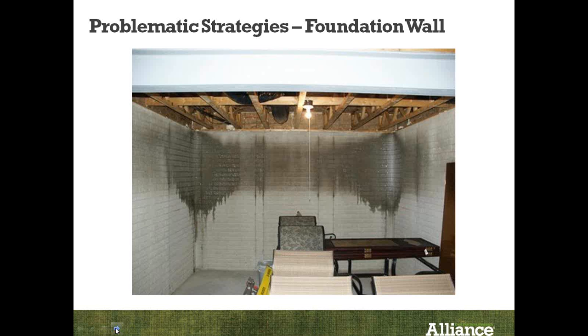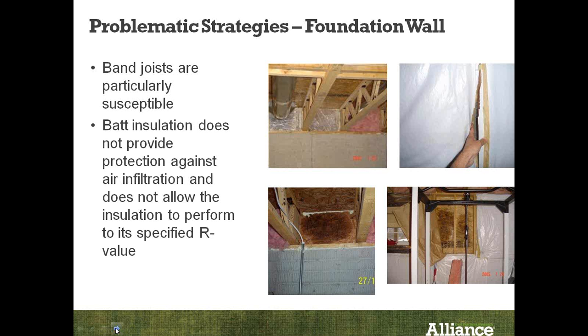The other aspect I want to talk about, in new construction, especially when we build basements, is that we do introduce a lot of moisture during probably the first 18 months of the home's life. Because concrete has a lot of water in it, it raises the interior relative humidity inside the basement and ultimately inside the whole house.